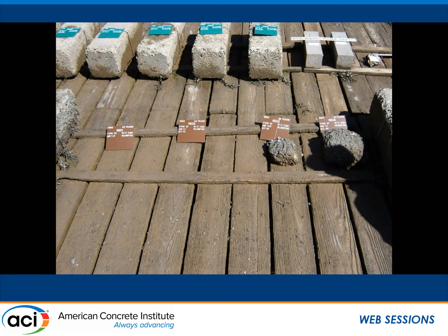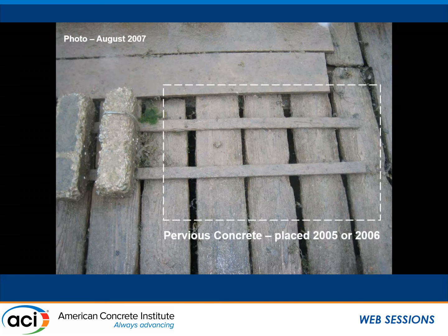It's not there anymore. This is some pervious concrete that was placed at Treat Island 2 years before I took the photograph. So I know pervious concrete is not designed to be in the marine environment with 100 freeze-thaw cycles a year, but if you are foolish enough to use it in that application, that's what it will look like. You can see here, there's a little piece left. We're actually subjecting that to very extensive microscopic investigations at the moment.